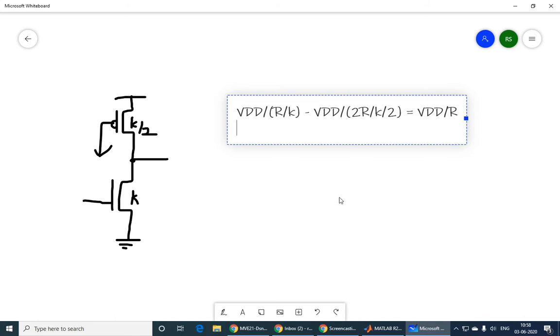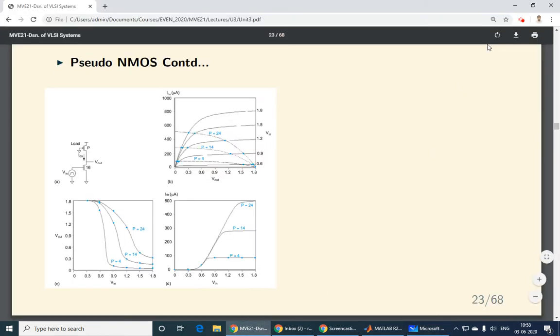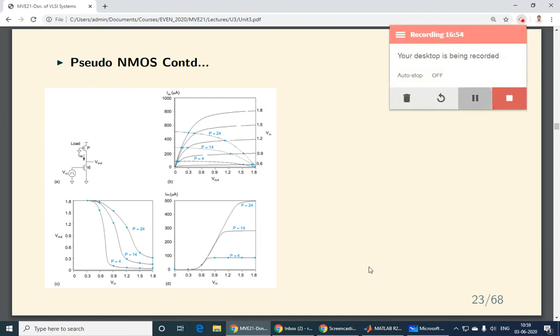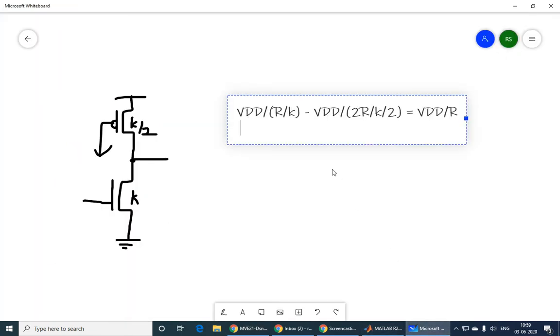Let's just solve for K offline and bring it back. Maybe that analysis was correct. So K I got is 4 by 3, which means the NMOS is 4 by 3 and the PMOS will be K by 2, which is 2 by 3, and this satisfies all the conditions that we require in terms of both the speed and the proper values for the output.